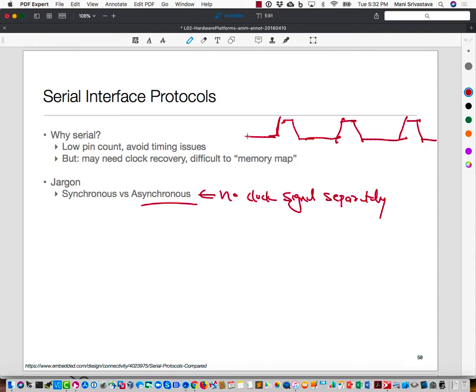Could you explain how come in parallel? Well, yeah, so like a parallel port, for example, it used to be just sitting at a particular address and I would just go and read it. Whereas for the serial one, you would need to have some hardware which takes those serial things coming in and maps it into a parallel one. Alternatively, you could imagine I read only one bit at a time and then in software I convert it into a corresponding parallel number. But that will be very clumsy. So remember, I want to write an 8-bit character to a peripheral. So some hardware has to take that parallel thing and convert it into serial, and some other hardware has to do the reverse. Okay? So it just needs some more information.